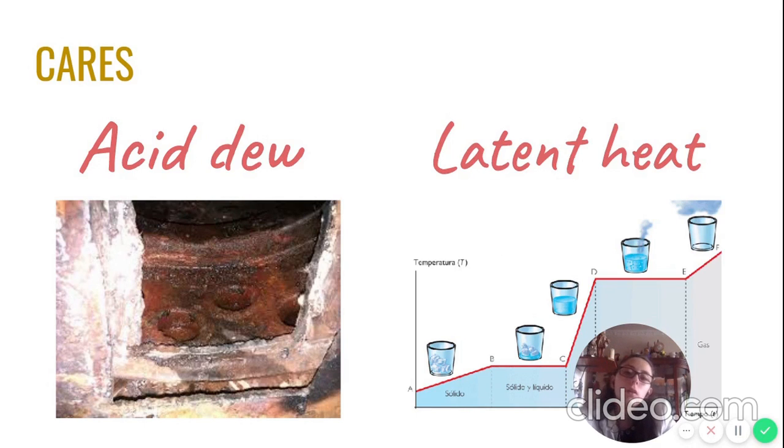If the temperatures drop too low, the dew point of this solution can be reached, condensing drops of high concentration. The acid dew phenomenon makes it necessary to reach an optimal value for the reduction of the gas temperature, balancing the energy saving of recovering more heat against the expense of reducing the useful life of the tubes due to corrosion.